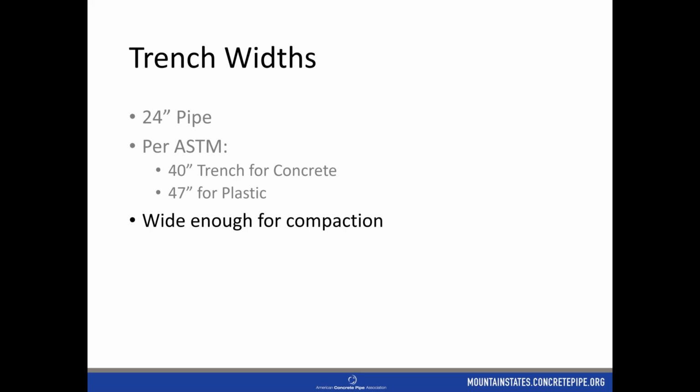I always just recommend make sure that your trenches are wide enough for compaction. That's always been my recommendation to contractors and inspectors and designers and people that are writing the specs. Just make sure it's wide enough that we can get the compaction that we need.